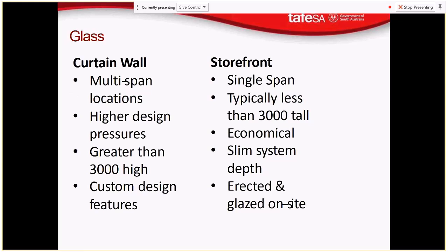So that glass isn't going to be taking a huge amount of pressure per mullion. So those mullions are taking all that pressure, whereas a typical curtain glazing scenario, we would have much smaller frames than that, and they'd be much further apart. So we have to have higher design pressures.